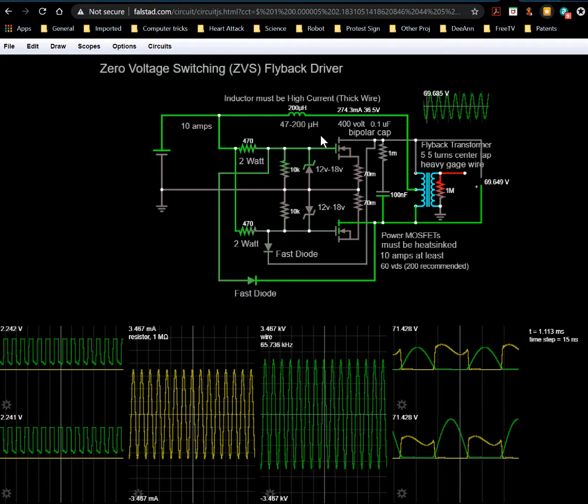Because of that, this transistor is allowed to stay on, because this gate voltage is high. It's 12 volts. However, since this is at ground, this right here is at 1.71 volts, whereas this right here is at 2.5 volts. In other words, you take 1.71 and add a 0.7 volt diode drop to it. That gives you that, but that's not enough to turn this transistor on.